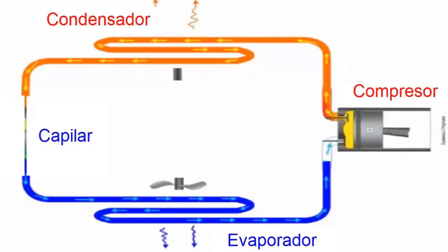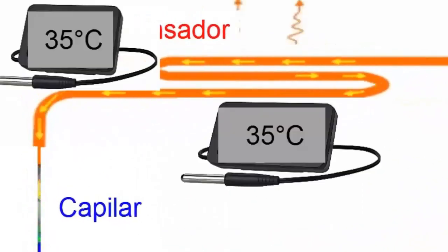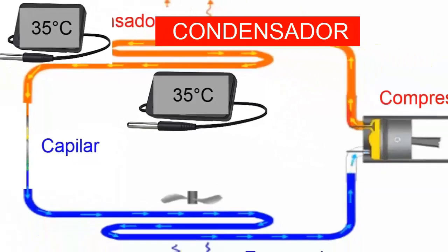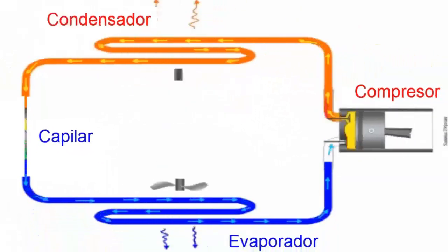Consequence 6. Let's recall that subcooling is the temperature decrease compared to the refrigerant's condensation temperature. When there is a refrigerant overload in equipment, a slight increase in condenser subcooling is recorded. This can be approximately verified by measuring the temperature of the environment outside the condenser with a thermometer and comparing it to the refrigerant temperature at the condenser outlet. These values are almost identical.